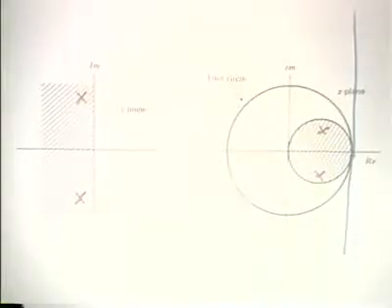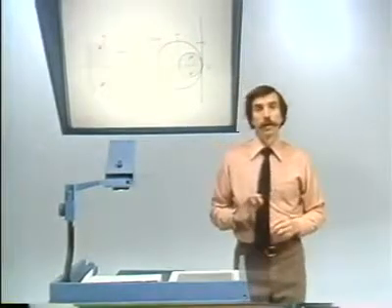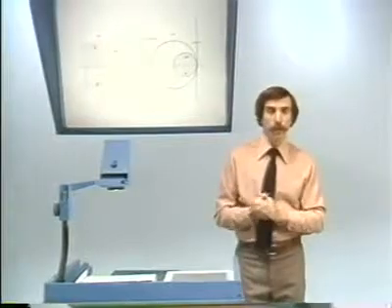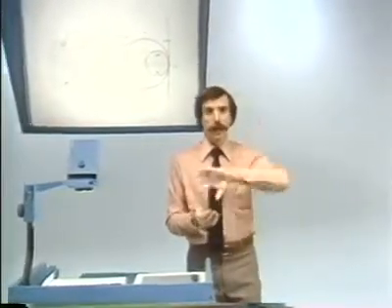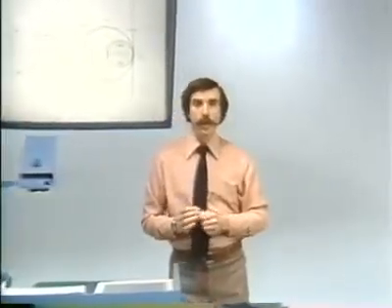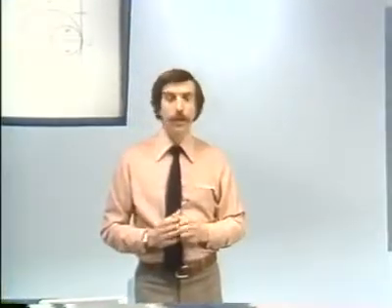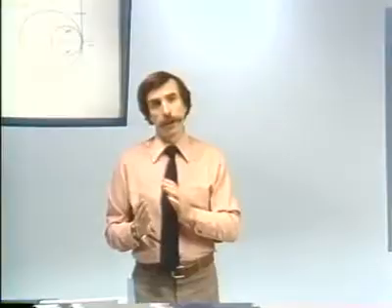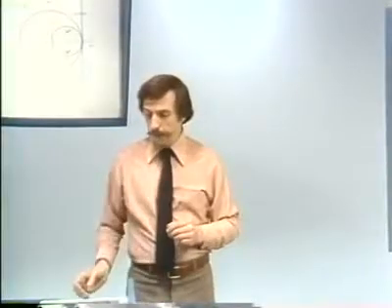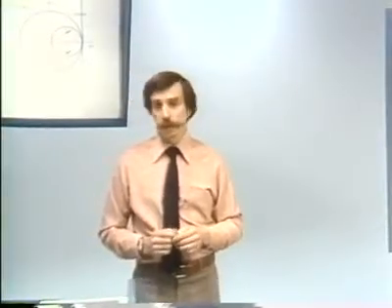So not only are forward differences equally bad in terms of the issue of whether they map from the j-omega axis to the unit circle, but they have a further difficulty associated with them, which is that they may not and generally don't guarantee stability.